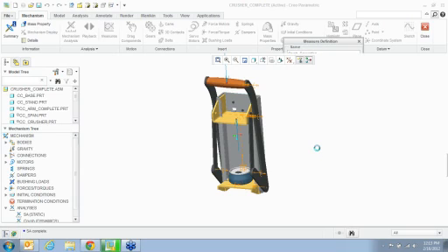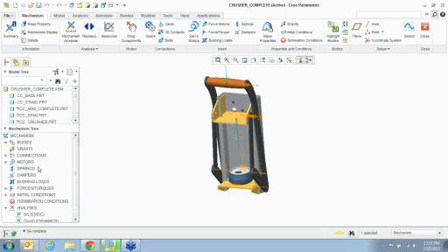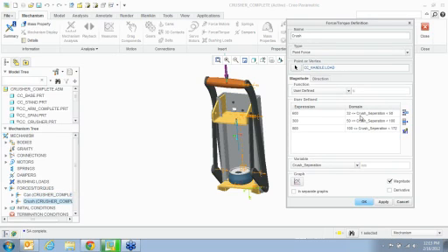What I tell it here in the force is that this force will act at a value of 600 when the crush separation, which is the distance between that point and this point, is between 32 and 50. The value of the force will be 300 when the distance between this point at the top and this point at the bottom is between 50 and 100. And it's 800 when the value is between 100 and 172.